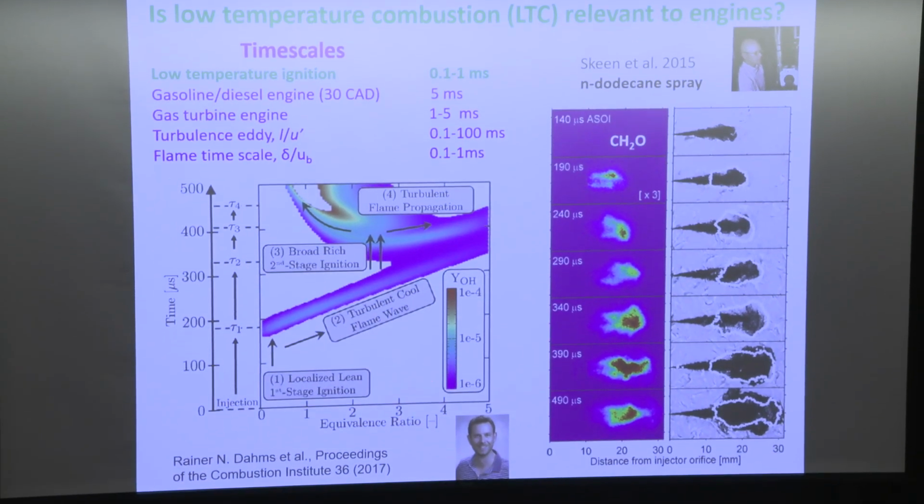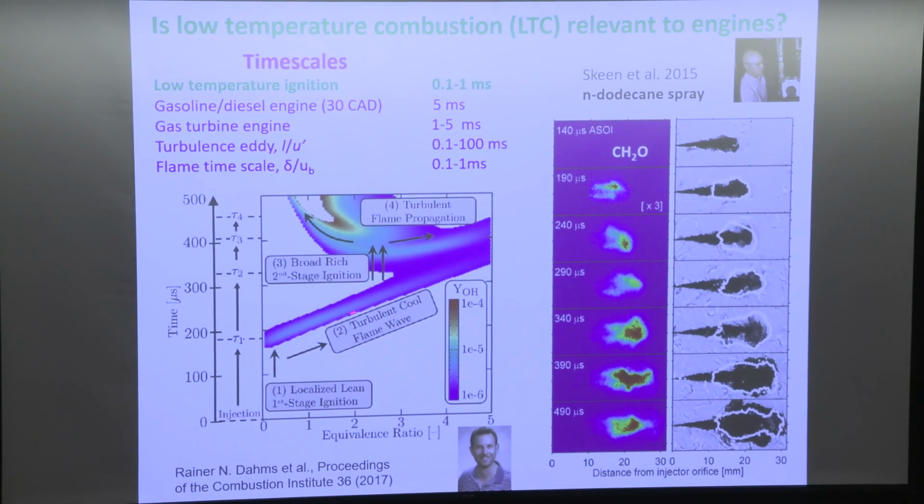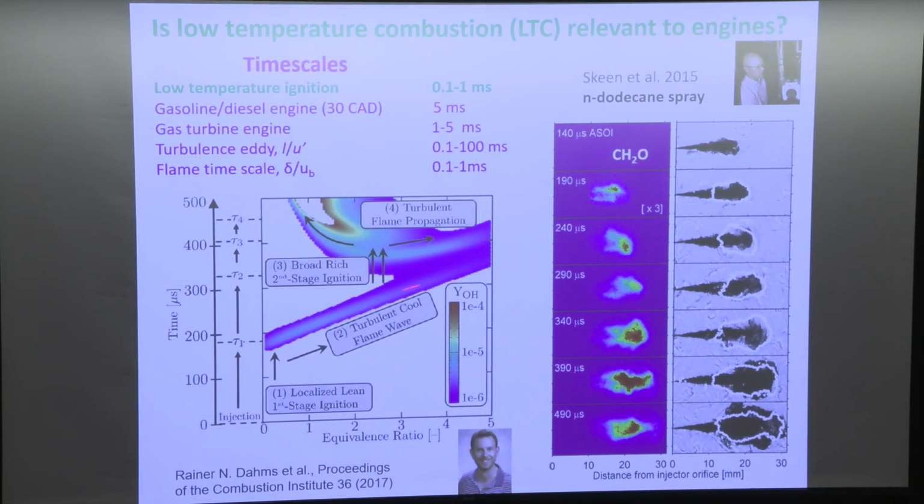Looking at the equivalence ratio, the rich condition doesn't need much temperature, and at these fuel rich conditions a lot of radicals are generated, OH radicals start to build up, and heat release starts to build up. Once the heat release and radicals build up, that triggers high temperature ignition. The high temperature ignition drives the flame back to stabilize at nearly stoichiometric.